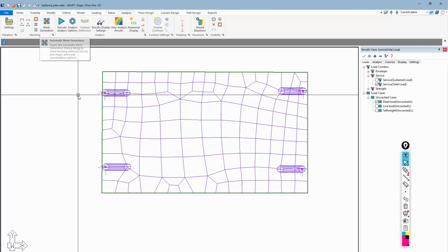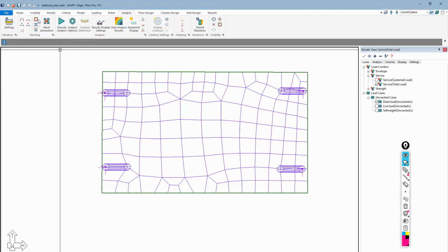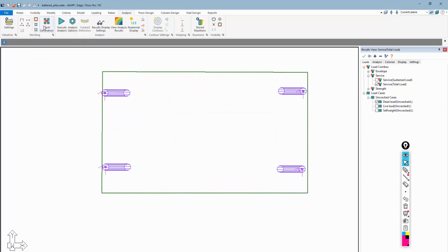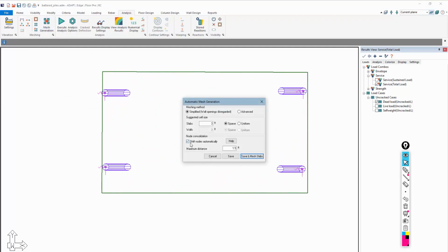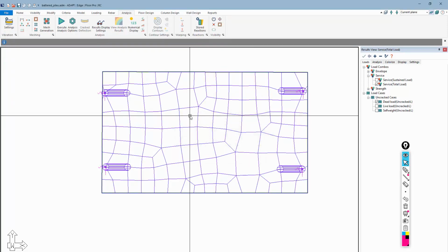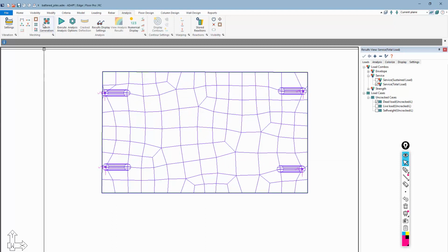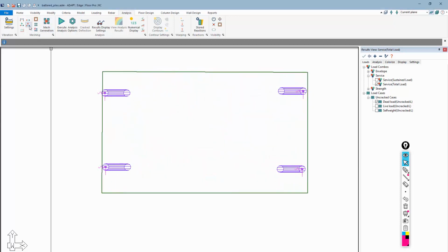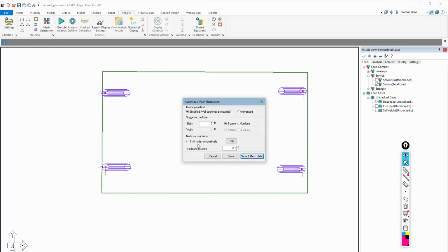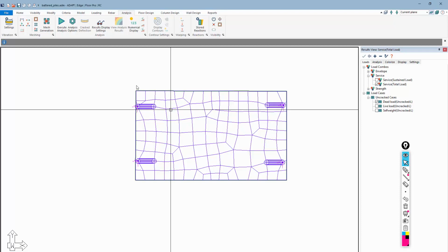So one thing that we can do here is I'll clear out the mesh. I can then remesh, and I'm going to either reduce the mesh size so that it's smaller than this distance between slab edge. So this might be like a 0.5 inch node shift. Now you can see it's connecting to the spring on those elements there. Or I can just simply turn off node shifting. For some slabs, node shifting might be useful. For this slab, we're going to just turn it off altogether. We still get a pretty good arrangement. And once I've done that, then I can execute.